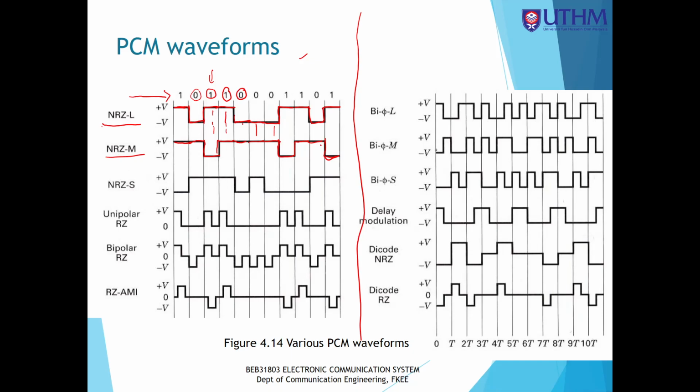This is non-return to 0 mark. And for non-return to 0 S, S means space. So S is the inversion of M actually. NRZ-S means that changes happen when the input is logic 0.